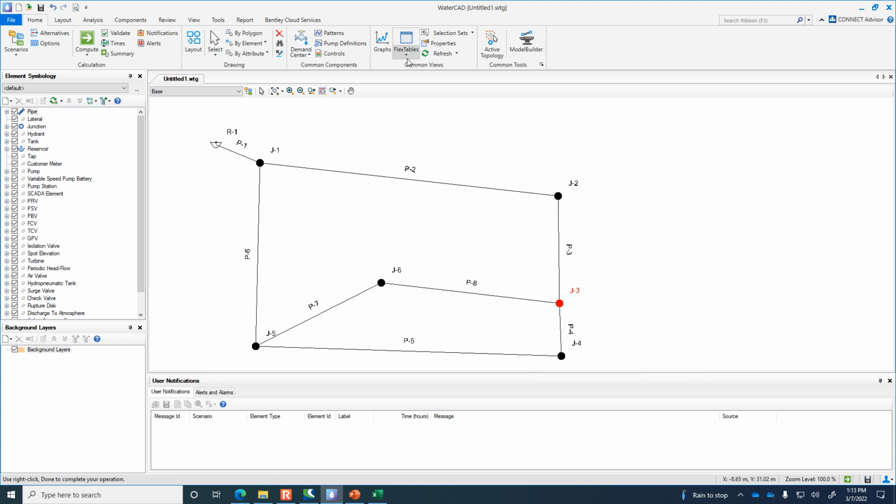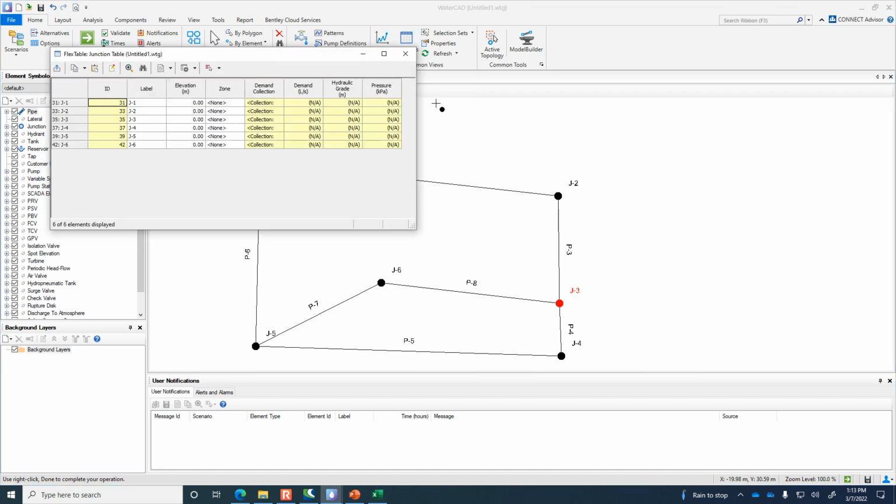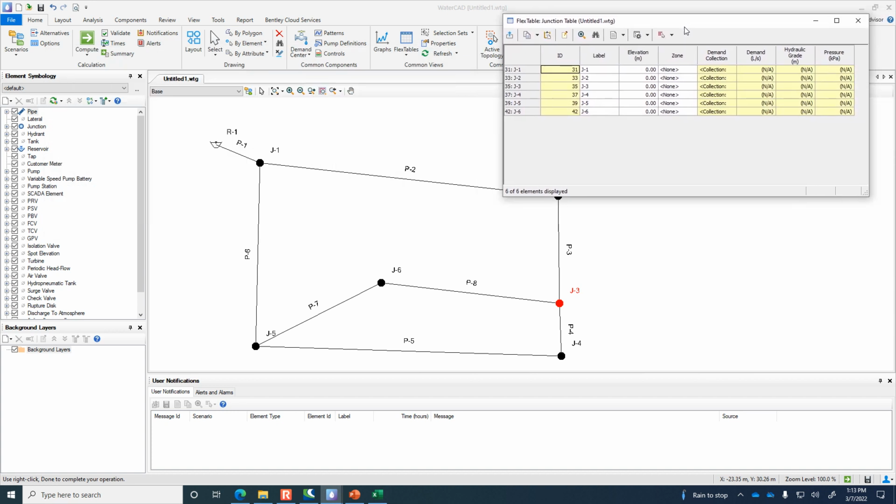And I'll take a moment just to rename all of the junctions so that it's consistent with what you've got on the handout. So maybe what you ought to do as far as note taking is just a bullet point of what I did step by step. So I'm renaming the junctions right now. You have a similar thing on your project where I've given the junctions names, and so your naming convention needs to be the same. Where it says J1, I want that to be called A, B, C, D, F, and E. All right, so the junctions are labeled.